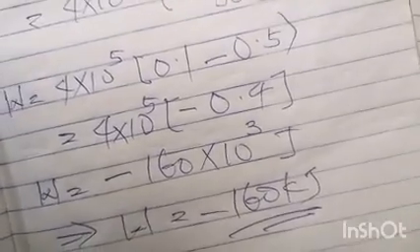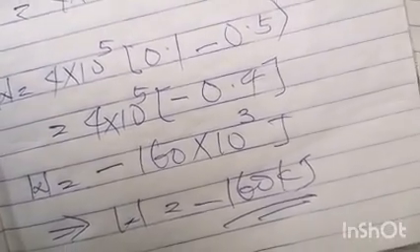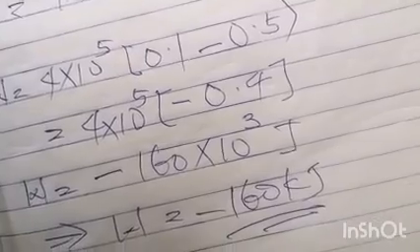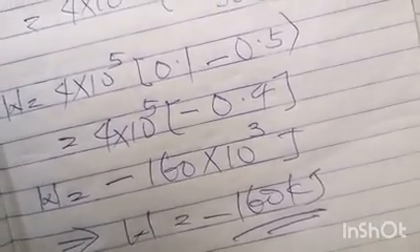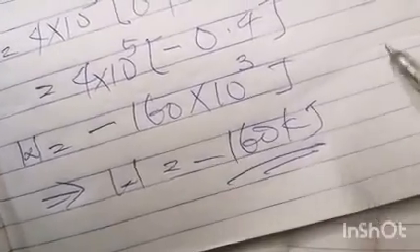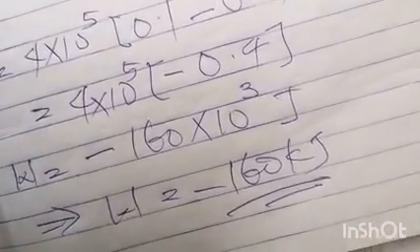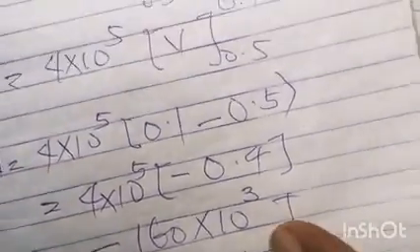You notice that they said the steam became cooled. Okay, so if the steam became cooled at constant pressure, that means heat has been removed from the system. That's why you have a negative value as the answer. So it becomes the work done. Okay, final question says we should find the heat transferred.